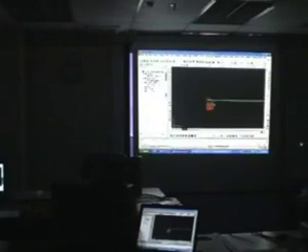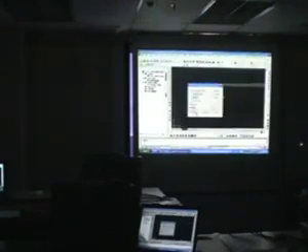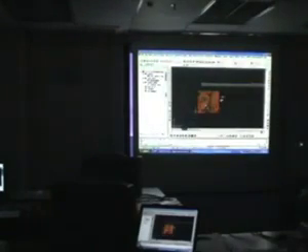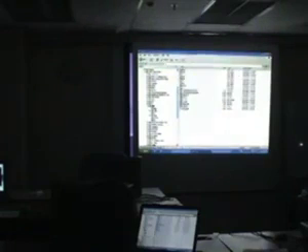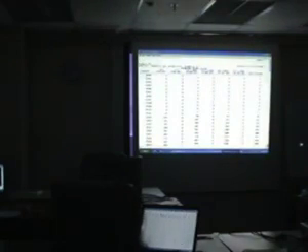Now, if you need the volume calculations by section, it was generated here under volume report. Okay, let's say I use the smile method. I'm just going to hit OK. And okay, now it's generating the text file. It's placed in here under the file name output.prn. I'm going to rename this to sections, and we're going to open that up so you can have a look at the section report.